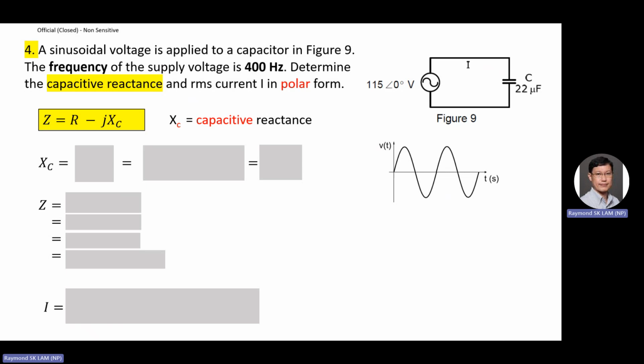And the formula will be something like that. If you have a resistor connected in series with a capacitor, for AC, instead of calculating the resistance, you calculate something called Z, the impedance. It's written here. So for AC, we always calculate Z impedance instead of just the resistance. So Z equals what? R minus j XC.